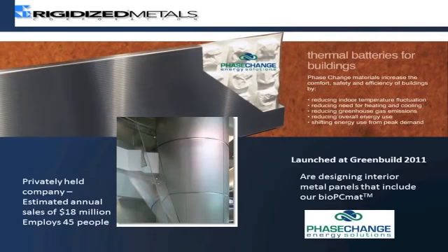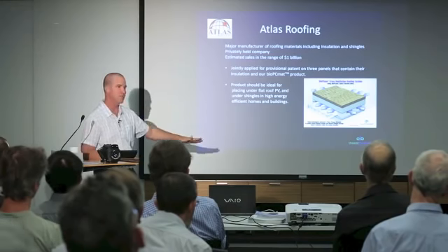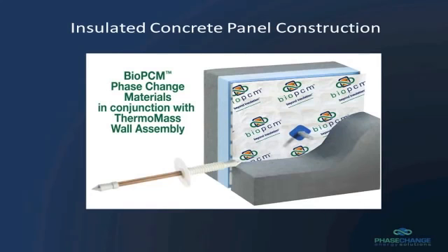This is a board product where we've got a timber layer, insulation and phase change, and then foam and then foil and insulation. That barrier there, you almost can't get heat through it no matter how hard you try. You can do it in wall panels. You could even lay it inside concrete in sandwich panelling to improve the thermal mass of the concrete wall.